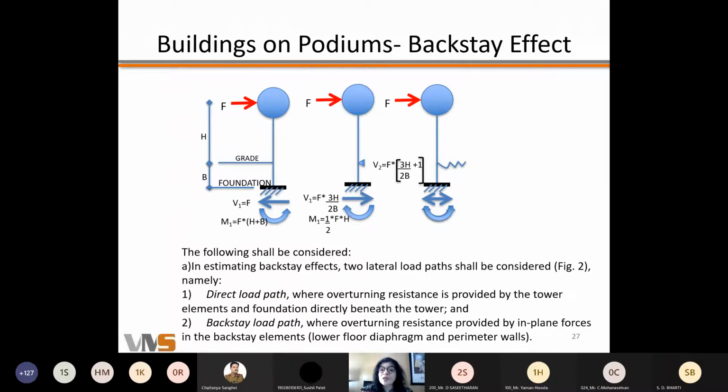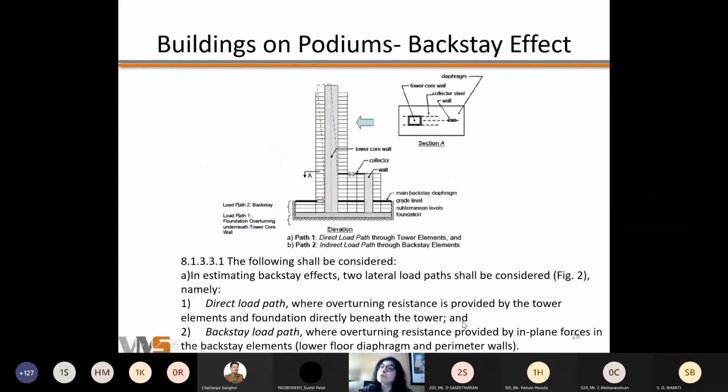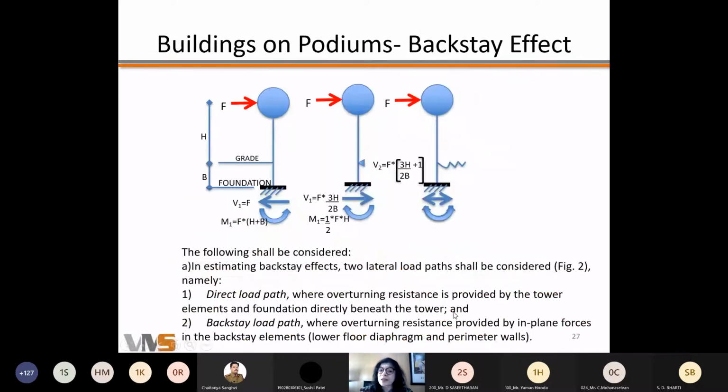And what is happening over here is that because you have this podium level, it's a kind of a support, but not a rigid support. So there is going to be now a transfer. The diaphragm is now extended, and the load path of the lateral loads suddenly changes, right? So therefore, this diaphragm is very important to be designed properly. And then suddenly, if you have cutouts and so on in the podium level, which very often you do have, there are issues.